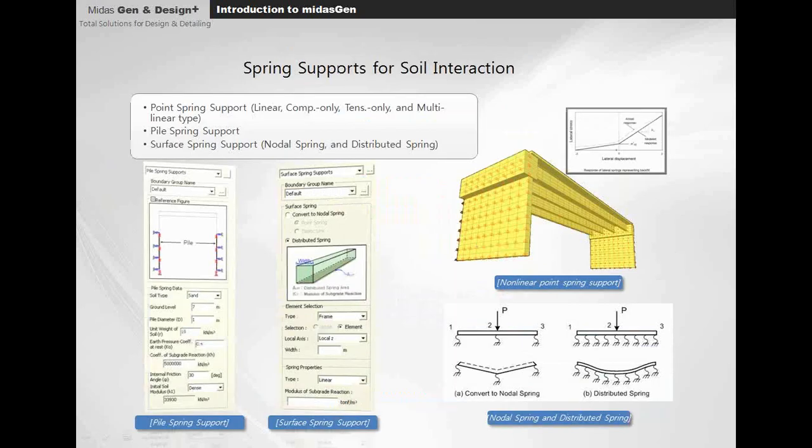Now, coming to the soil interaction. Now, this is very important when it comes to the basic footing and the foundation analysis. We can model soil as multilinear springs to take care of the soil stiffness, and the non-linear characteristics of the spring over the pile height are automatically calculated. So when you get the displacement, you can easily calculate the forces and the stresses developing.